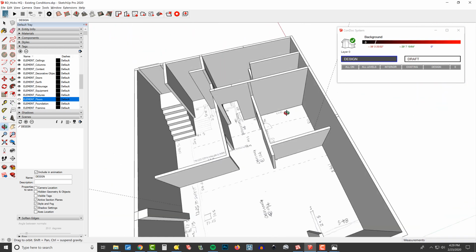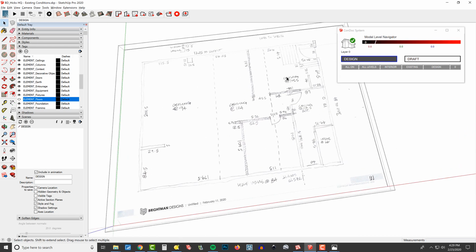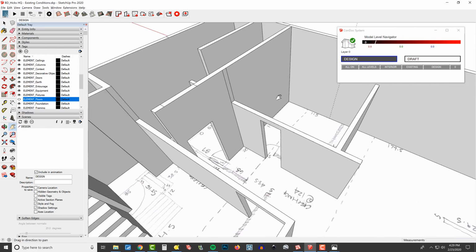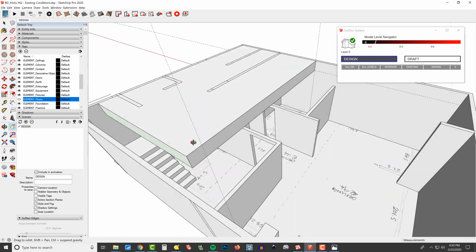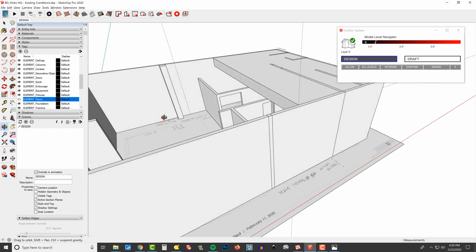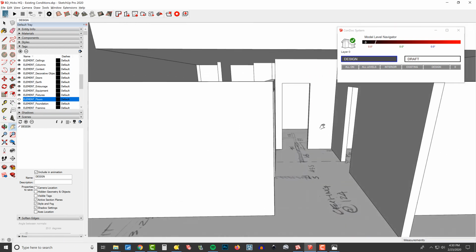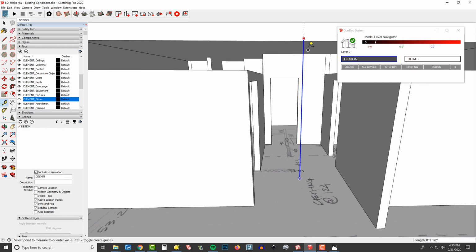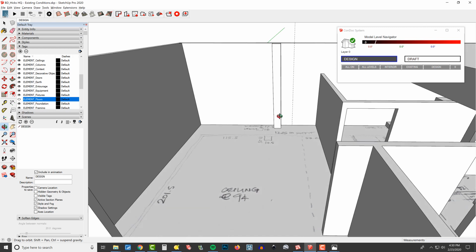But this ceiling here is at 105.5. So I'm going to drop a big block at 105.5, and draw it all the way back like that, and then use my push-pull tool and pull it all the way over here. So that's where that soffit drops in this space. Now we've got that at our perfect 105.5, 96, 105.5. Yep, we're good. And then this guy over here is at 94 inches.